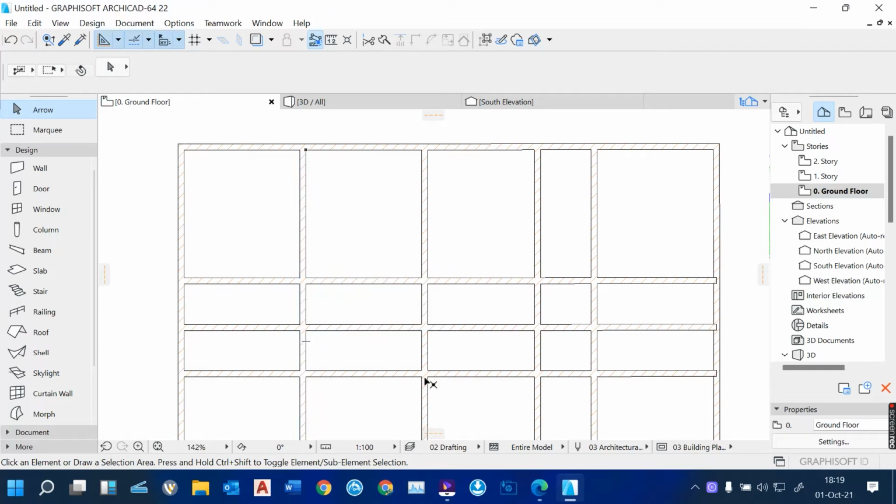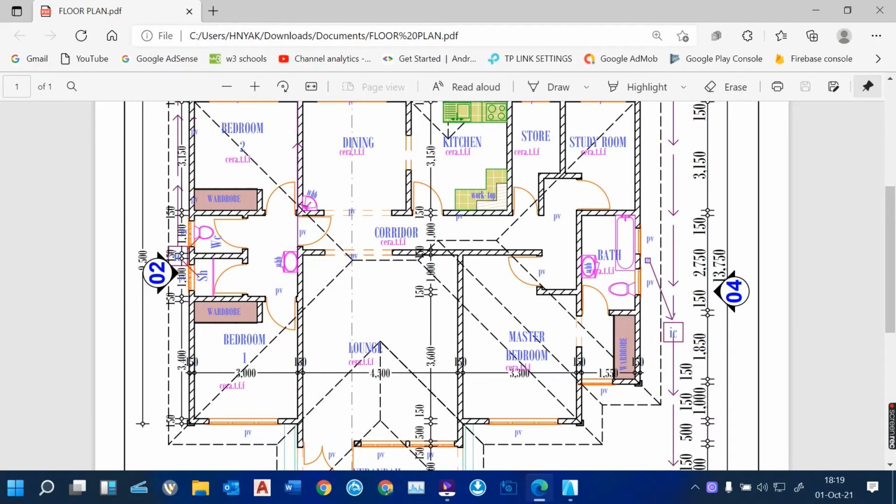We are still continuing to do our partitions. When you look into this drawing, we have done this partition and this other partition. So we can trim and leave other places for doors and windows as well. So I want to trim this area because this is an opening. This is also an opening. I want to remove this second one and also remove the third one by trimming at this particular point.